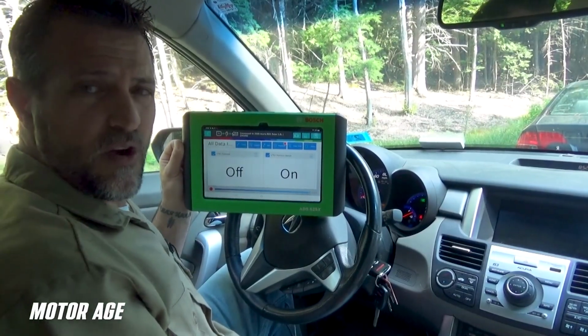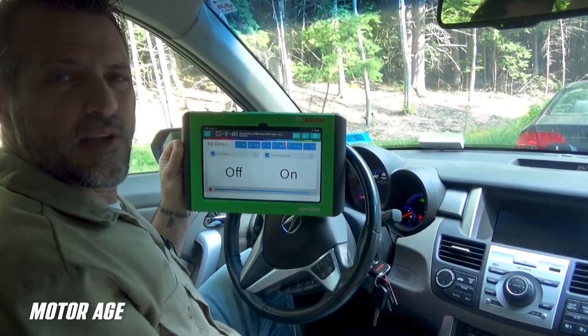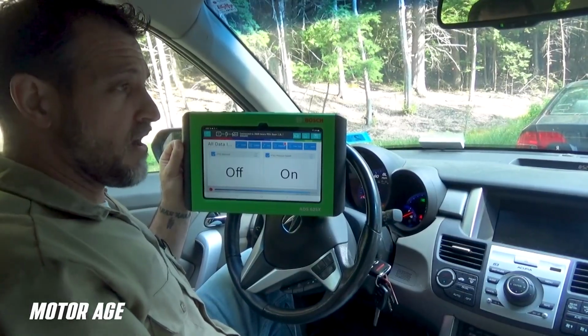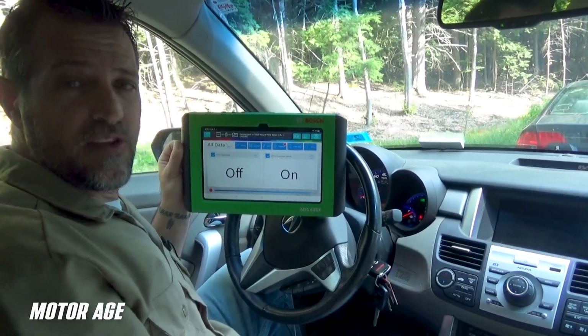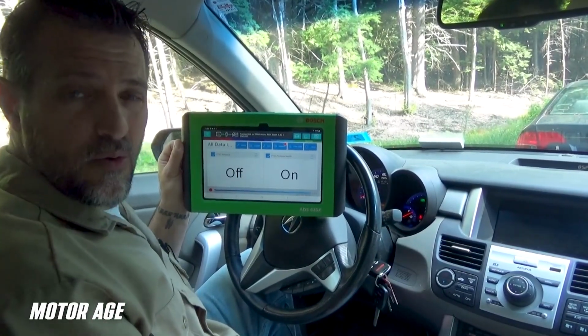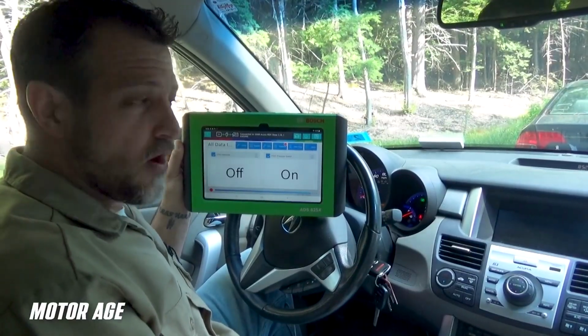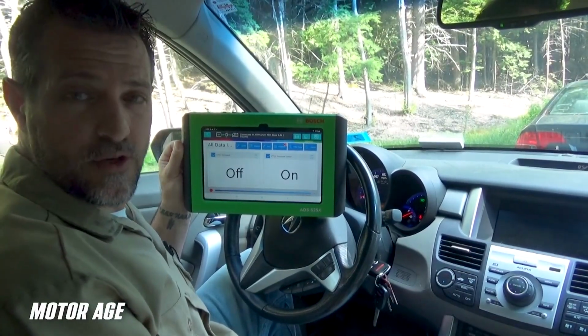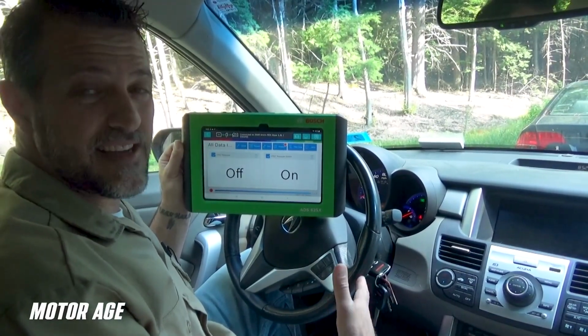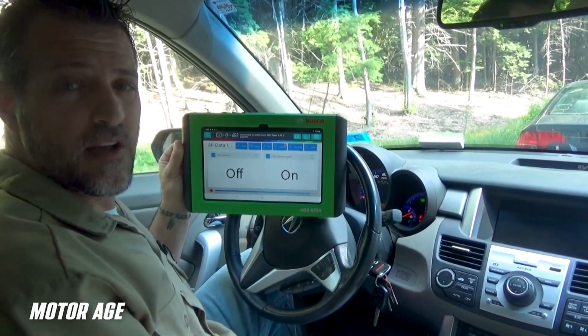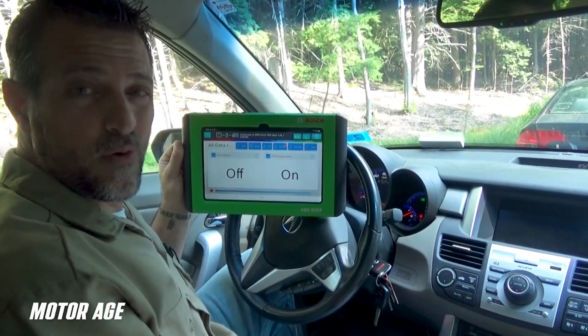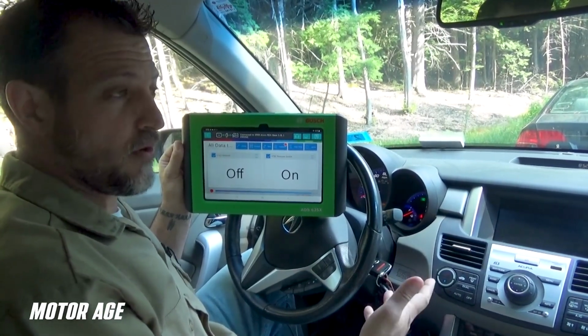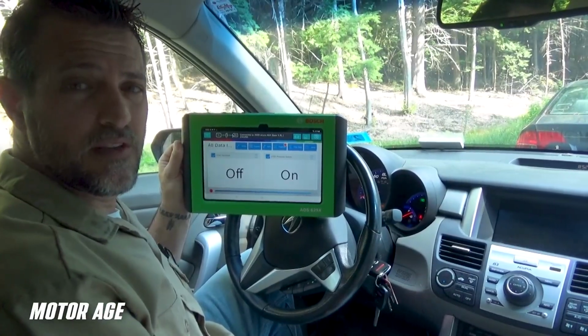Do we want to start going under the hood and looking for potential faults? In other words, are we dealing with an oil issue? In other words, oil is low or oil is contaminated? Are we dealing with a solenoid issue, as in the PCM intended to actuate the solenoid, but there's an electrical circuit fault in that solenoid's path, or the solenoid itself is faulty?